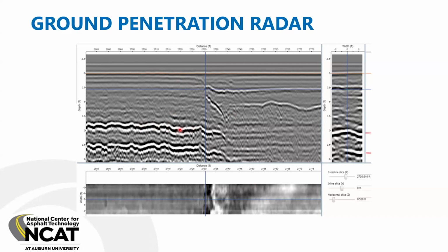So if there are utilities like the water main that Buzz mentioned earlier, or just an irregularity, something going on funny underneath the surface that is not readily apparent, that will show up on the GPR. And here you can see how there's an abrupt layer change. Again, you may not be able to tell if this is 2.5 inches, but you can start to see, on a macro scale, and pick those irregularities out.